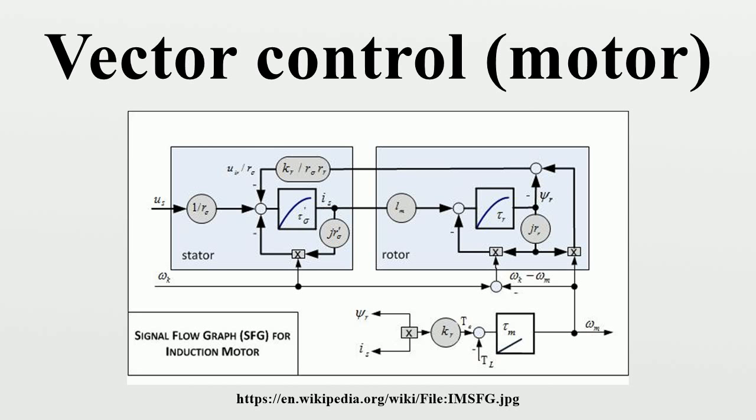linkage created by the respective field and armature currents are orthogonally aligned such that when torque is controlled, the field flux linkage is not affected, hence enabling dynamic torque response. Vector control accordingly generates a three-phase PWM motor voltage output derived from a complex voltage vector to control a complex current vector, derived from motor's three-phase stator current input through projections or rotations back and forth between the three-phase speed and time dependent system and these vectors rotating reference frame to coordinate time invariant system.